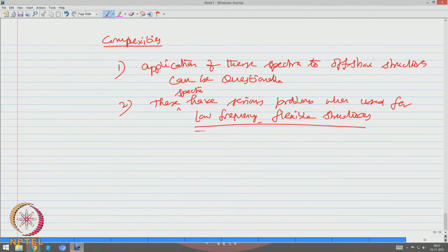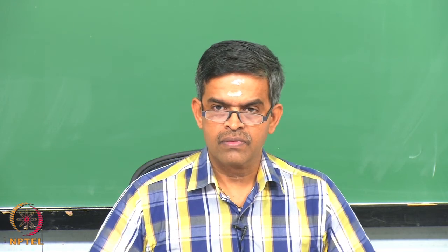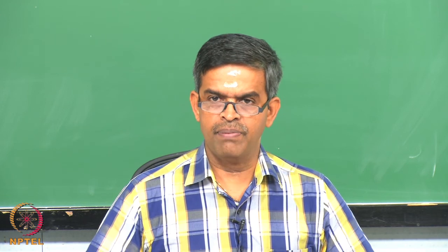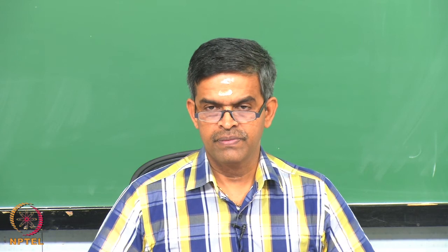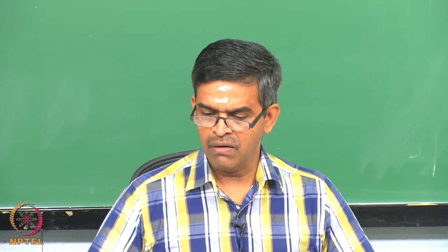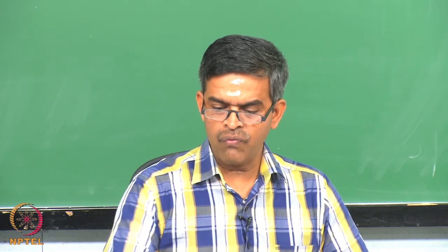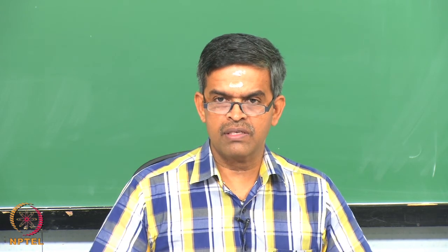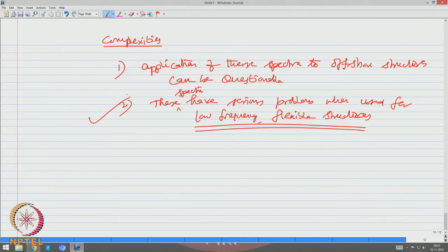This is the catch, because we are discussing hybrid structures where there are two sets of frequencies, one is extremely low with a very high period, the other is extremely high with a very low period. So, when we have a structure which is flexible, what we say is compliant, with a low frequency dominance in its response vibration characteristics, using these spectra will have problems.